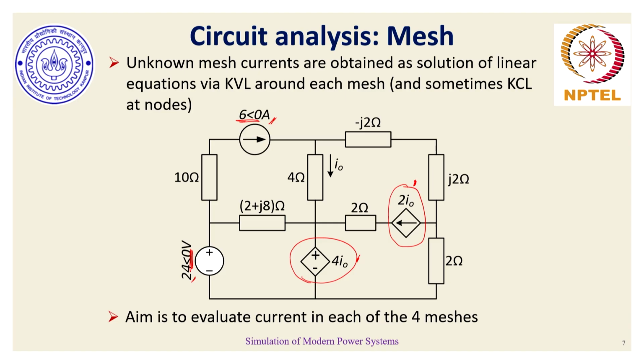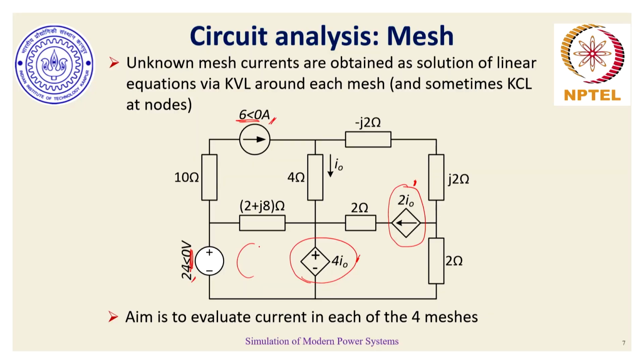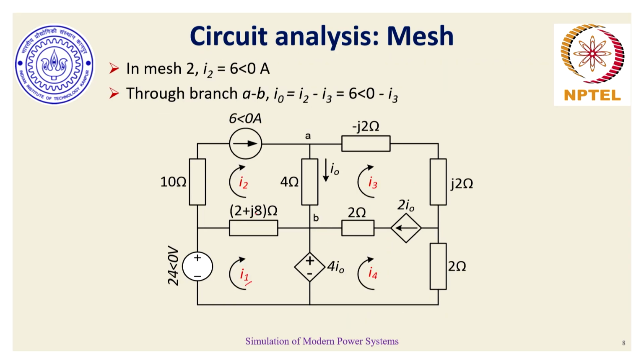In this circuit, if we identify the 4 meshes, a mesh is basically a branch or loop in a circuit. If we identify those unique meshes and then we superimpose all those meshes, our circuit remains unchanged. It is defined in the least minimum number of meshes. So in this given circuit, we can easily see we have 4 unique meshes. And if we assume that these 4 unique meshes have their respective currents I1, I2, I3, I4, again just based on direction assumption, these current directions may be different, which our numbers will eventually take care of.